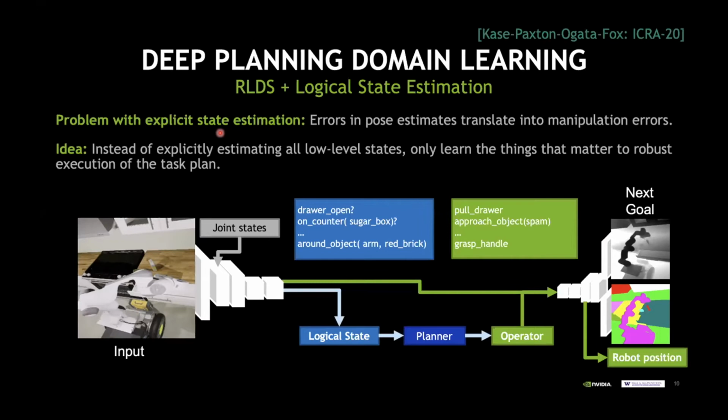So for example, to put the gripper on top of the object or things like that, right? In addition to the gripper position, we also impose an additional loss during training, such that the network is forced to predict, for example, the future depth camera image and the future segmentation of the scene, but these are actually not necessary for the actual task execution. The task execution really focuses on this next position that the robot should reach in order to execute that operator.